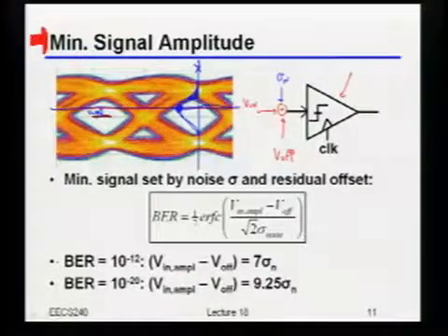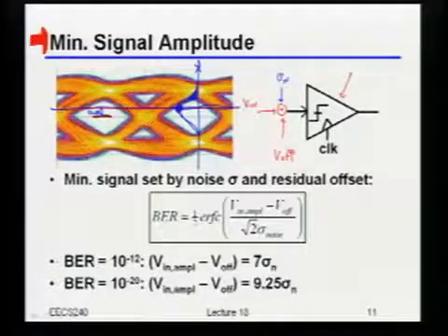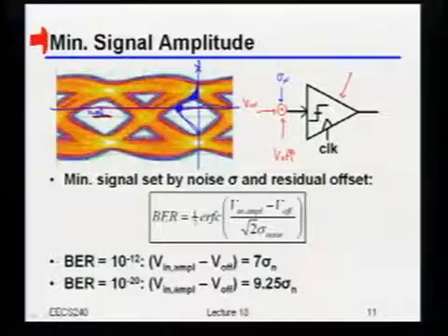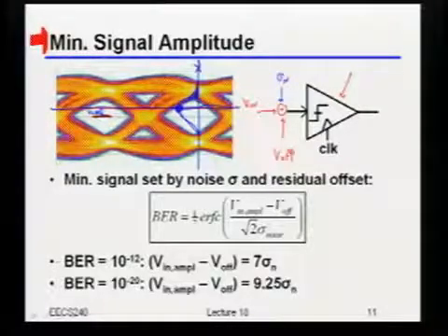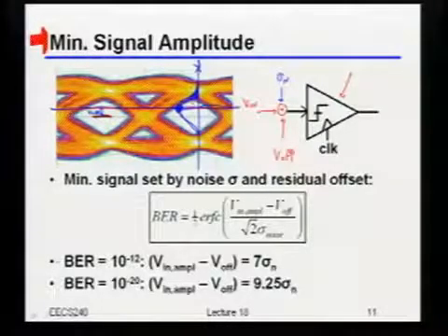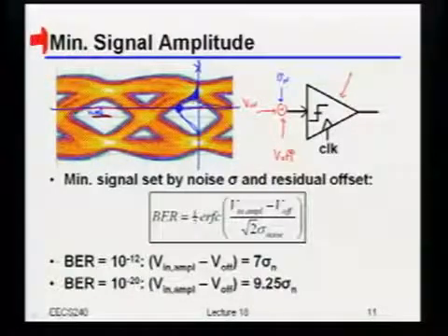So what I'm really interested in is exactly this shaded area, because that's the total probability of getting noise that's larger than the difference between my offset and my input signal right there.